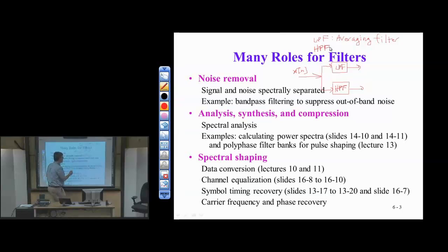So if we look at the impulse response here, I have a filter H0, and I have a filter H1, and we know from previous discussions that H0 is just a 2-tap averaging filter, so in terms of an impulse response, it's 1/2 of the discrete time impulse plus 1/2 of the discrete time impulse delayed by one sample.